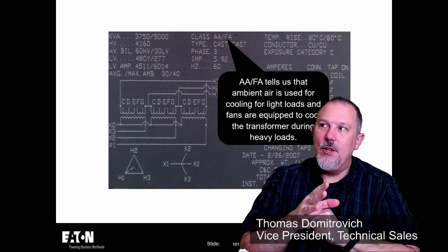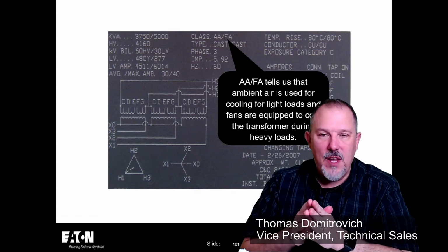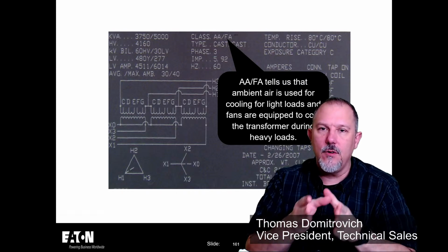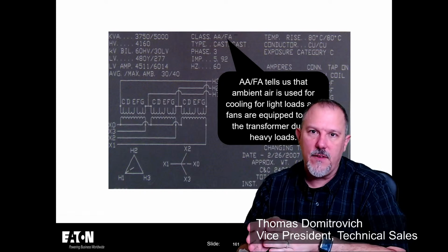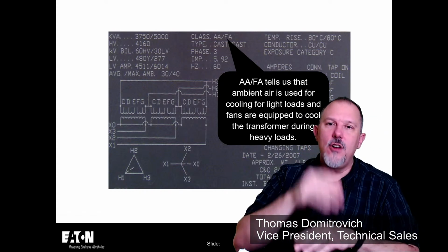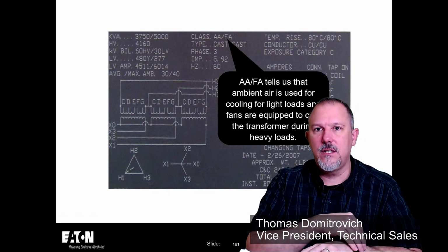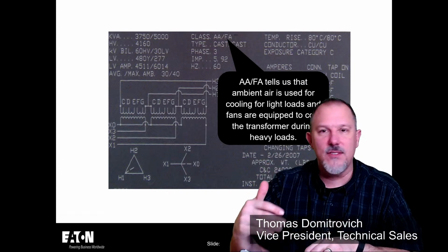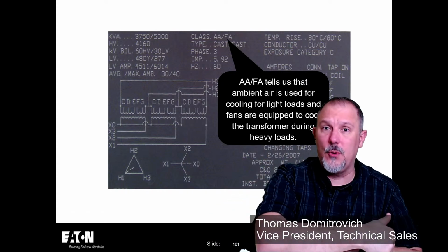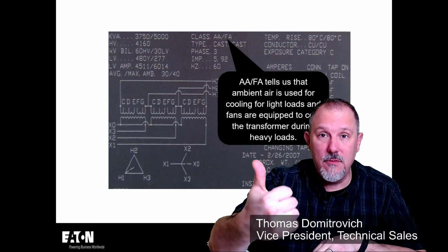Now, this tells me that I'm changing the full load amps. Think about it from your primary overcurrent protective device and your secondary overcurrent protective devices. If you're not sizing your devices to be able to handle 5000 kVA and the full load amps at those values, then your breaker is going to limit what you're going to put through this transformer.